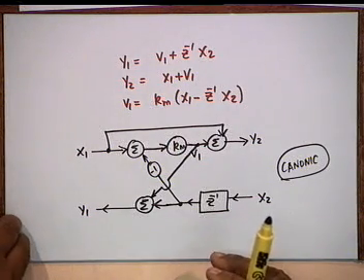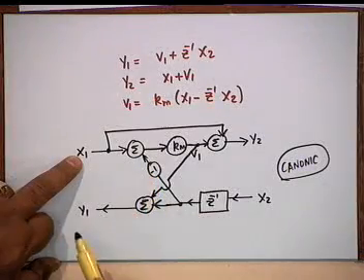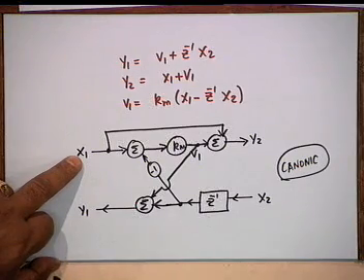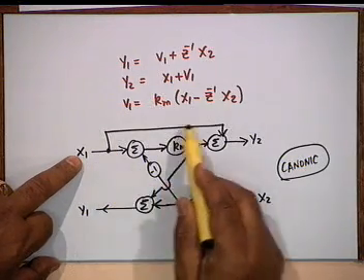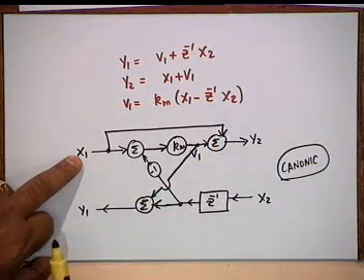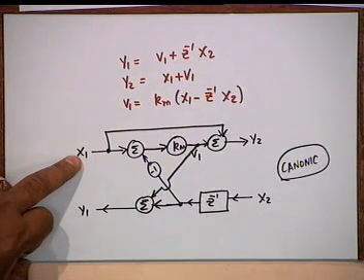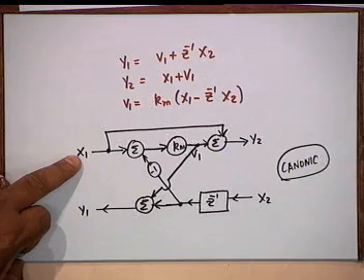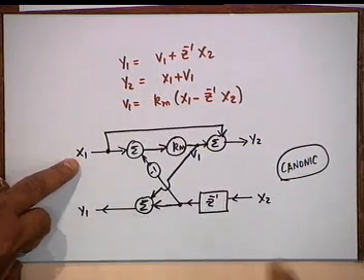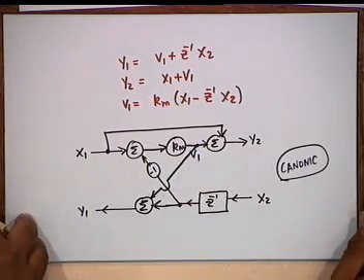I do not know. Where is the delay free loop? X1 to y1. There is no delay free loop. This arrow is in the other direction. x1 to y2. No, there is no loop. This is why the arrows are so important, to show the direction of signal flow. There is no delay free loop. If there was, then this structure would have been an invalid structure.